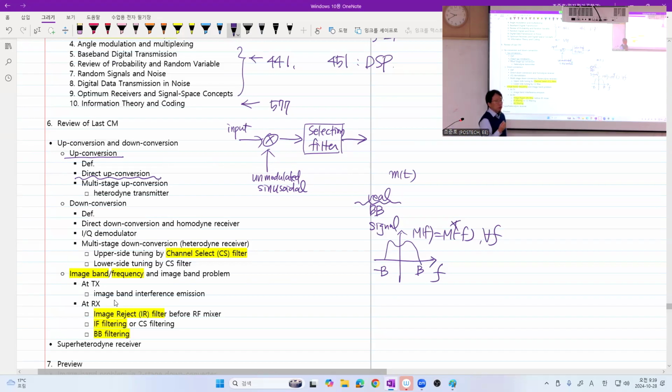the objective to transmit speech signal, which as an electrical signal is a real valued baseband signal. They mostly assumed this, but not necessarily. Got it? So this is a kind of zero frequency signal. Center frequency is 0. Now what you do is that you multiply by an unmodulated carrier. Then what happens in the frequency domain?